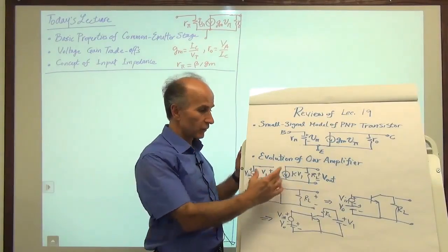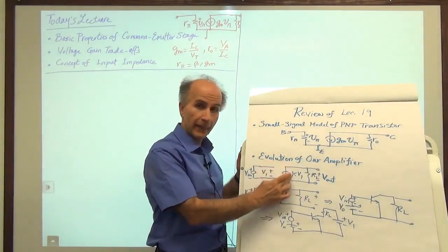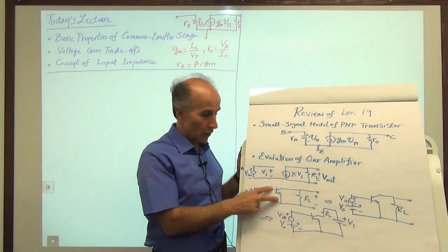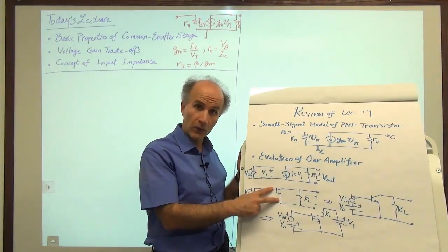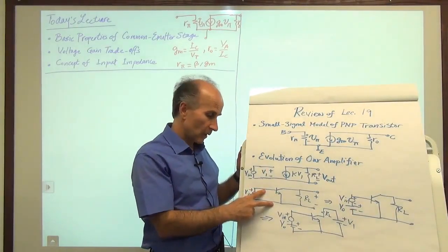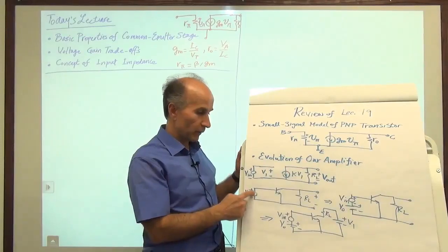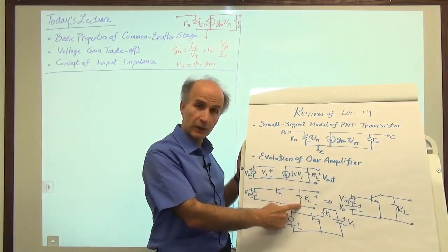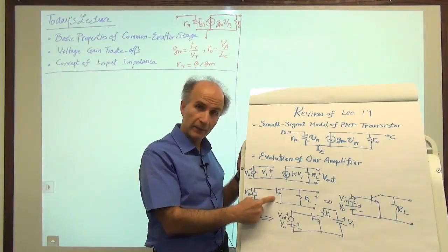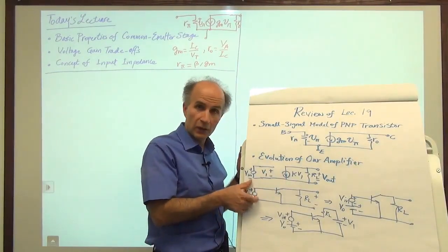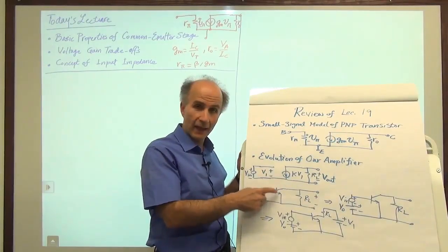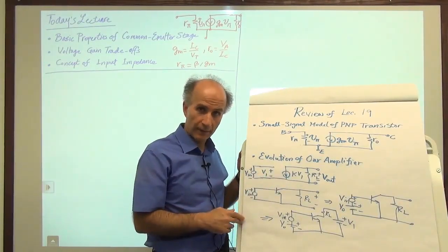Later on, we decided to replace this abstract device with a bipolar transistor, knowing that the bipolar transistor is also a voltage-dependent current source. So we applied our microphone signal here and put a resistor here, but then we realized that there is no bias current. If the microphone signal changes by a few millivolts or tens of millivolts, this device is dead, there is no amplification.